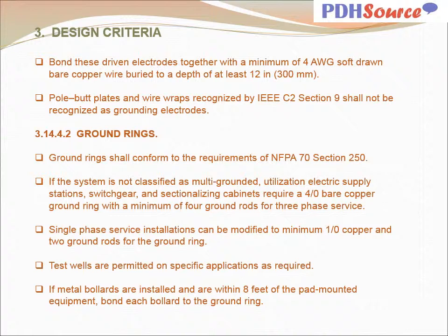If metal bollards are installed and are within 8 feet of the pad-mounted equipment, bond each bollard to the ground ring.